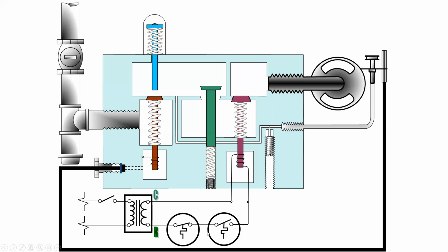Now, there's a few other additional items that we see in the electrical circuit, which is the high limit, and we're not going to focus on that too much here. And then we also have a transformer and an electrical disconnect. What we more want to follow is the sequence of operation that takes place. All right, so first thing we need to do is allow gas to flow into the initial chamber. And so we have a shutoff valve here. We're going to open the shutoff valve.